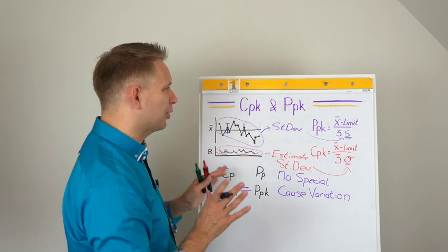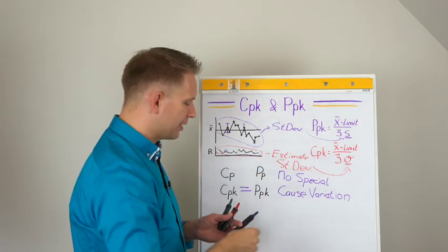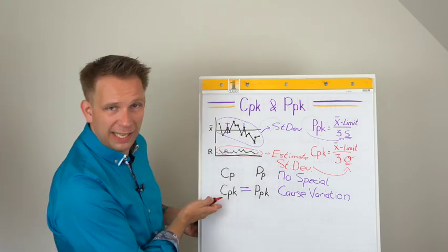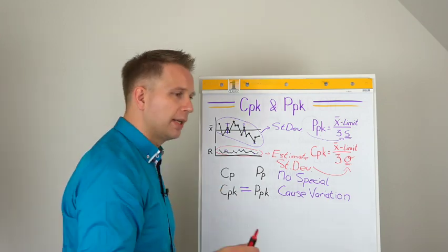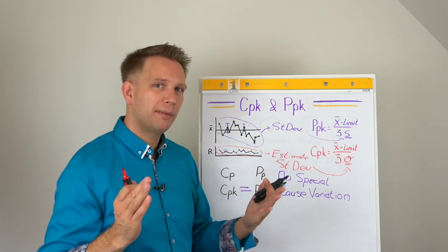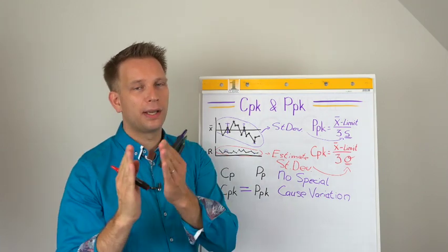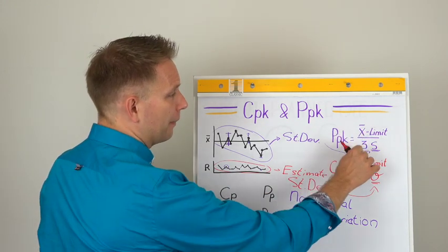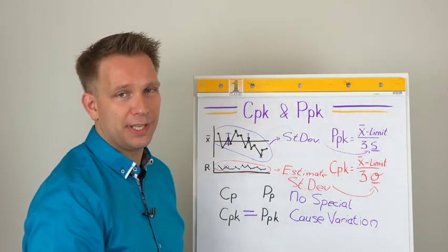Another one we haven't really talked about that much, but remember that I mentioned in the beginning that it takes the lowest of the limits. Well, what you will probably know is that there is also this Cp and Cpk, Pp, Ppk. This K coefficient is the difference between just checking how well the spread might fit between your upper and lower limit and checking the average and the closest limit and checking how close we are to that. So the formula for that one would actually be the limits, upper and lower, the difference between them, divided by 6 times the standard deviation.